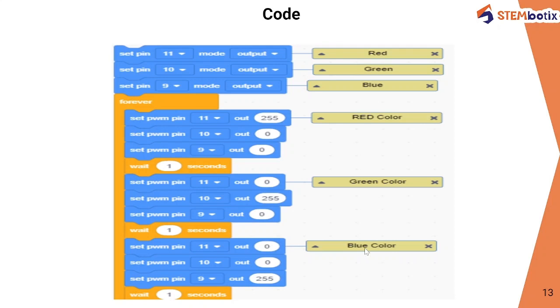First of all, we need to understand what PWM is. Let's have a look at a basic scenario of a PWM pin. Actually, the brightness of the LED is proportional to the current going through it, but it would be rather difficult to use a microcontroller to accurately control the current flowing through an LED. Fortunately, human vision has a nice phenomenon called persistence of vision. Persistence of vision is the phenomenon where an image that is seen for only a fraction of a second continues to be seen by your brain even after the original image has vanished or been removed.